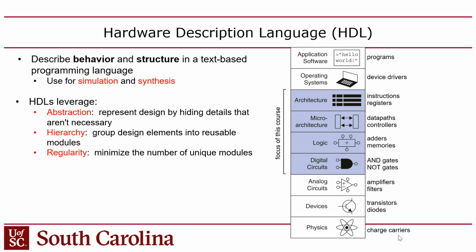So you'll make one component which might have 10,000 transistors if it's an ASIC, or 10,000 gates if it's an FPGA design. But then you instantiate it, you stamp it out 100 times, right? And so even though the code that does that is really short and simple, the amount of design that's generated from that in the CAD tool as it expands each one of those instances is huge, right?